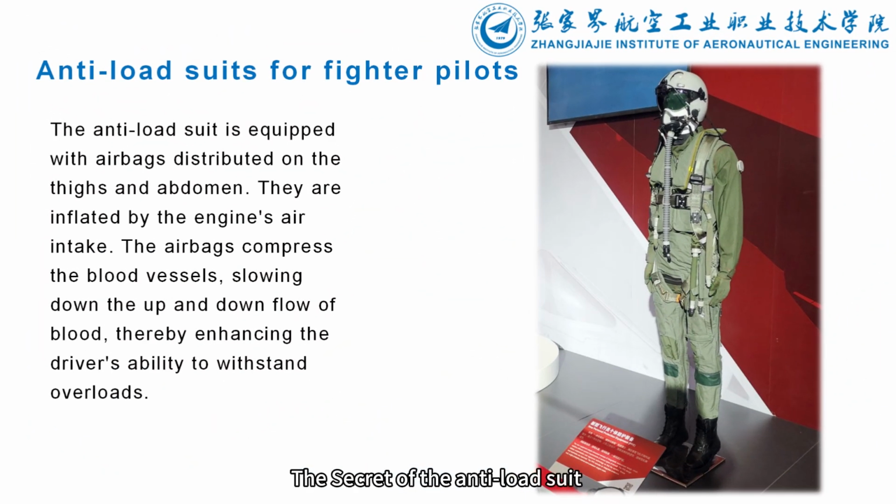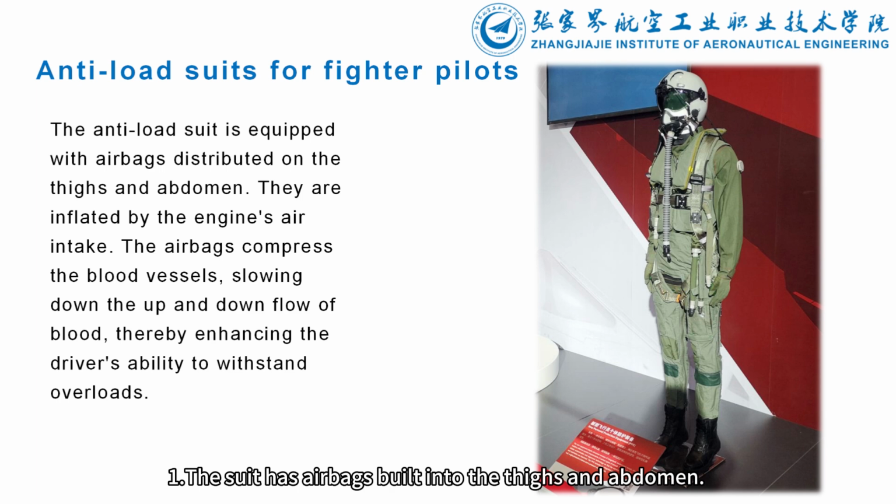Fighting high overload, the secret of the anti-load suit. Just mentioned the anti-load suit for fighter pilots. Let's take a look at how it works. 1. The suit has airbags built into the thighs and abdomen. 2. When the aircraft is subjected to high overload modes, such as a large angle lift, the system uses compressed air drawn from the engine to rapidly inflate and pressurize the airbags.